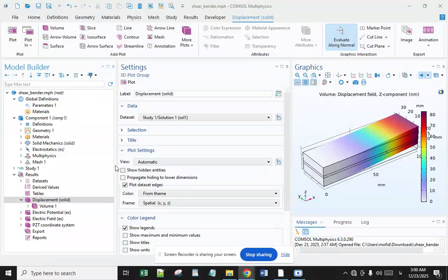Additional parametric studies on actuator position, thickness, structure stiffness, which the present element permits, indicate that the shear actuation mechanism presents several promising features over the conventional extension actuation mechanism. In fact, the shear actuation mechanism is better than the extension one for stiff structures and thick piezoelectric actuators. Recent and current research efforts in the field of structural control using active materials are directed towards improvements of the actuation capacity of these systems.